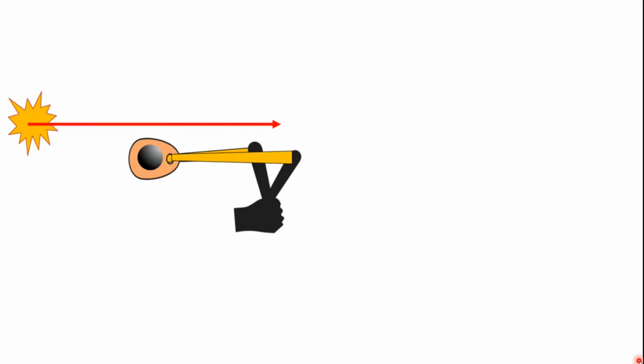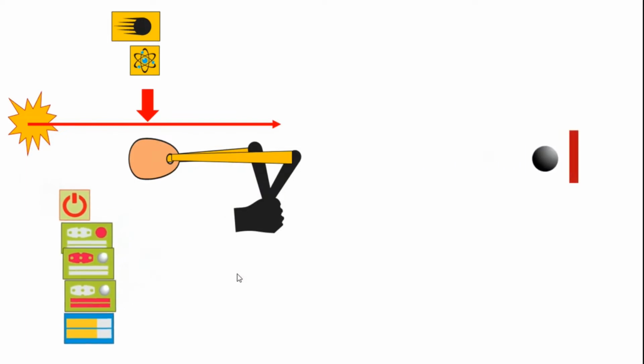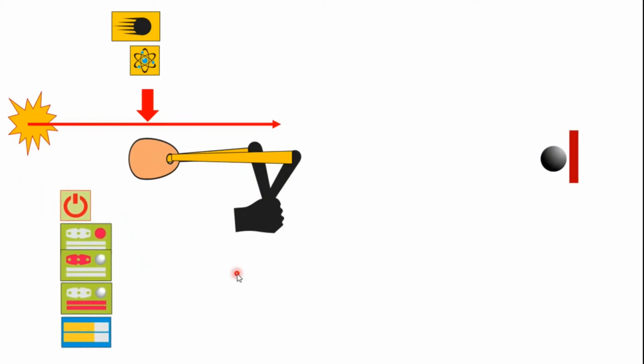So let us review main elements which we encounter when we speak about slingshot ballistics. First, we said there is a very special point which is somewhere halfway between your full draw and the fork tips, where the pouch stops accelerating the ammo and where the ammo receives its exit velocity and exit energy. The variables which determine this velocity and energy are draw power, the weight of the ammo, weight of the pouch, weight of the rubber itself, and elongation, which is, as you remember, the difference between your full draw and active bands.